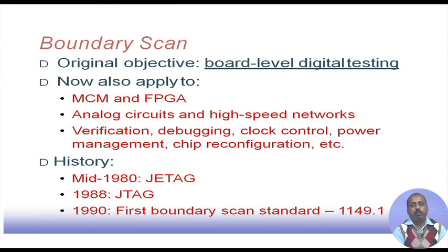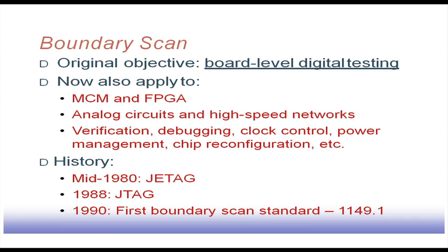In an FPGA also, the design is very much modular, because we have a similar set of configurable logic blocks distributed throughout the chip. If you want to test each of them, then we again have to send some test pattern to each of these CLBs, and that can be done using some chain architecture, so that the test patterns can be fed to the individual inputs of the CLBs. So that way FPGAs also have boundary scan.